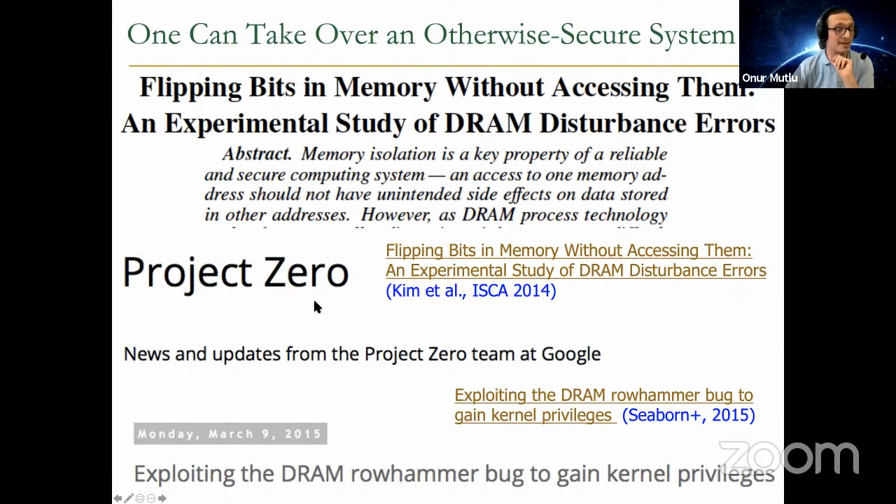I'm actually going to talk about this a little bit more when we get back to virtual memory, because what RowHammer does is whenever you hammer a row, you really induce bit flips in adjacent rows, physically adjacent rows, but those physically adjacent rows may belong to other applications. They may belong to the operating system. So you're really breaking the memory isolation properties of the system. And when you break memory isolation properties like this and induce predictable bit flips, someone can take over your system.